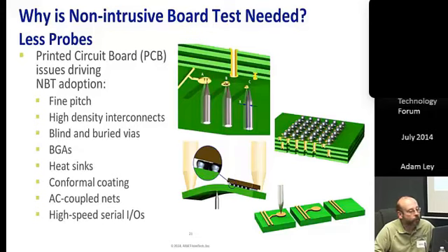That leads to complication for probing. And just generally then the high-speed serial I/Os. The illustration that you see over here in the lower right-hand corner, if it was fully implemented, would have a set of I patterns associated with it that on the right-hand side show a more or less open eye, indicating that there's no interference from the test points or probing in terms of the signal integrity on that pair. But as you add a test point, you get compromised signal integrity, and of course as you probe, even more so is your signal integrity compromised.